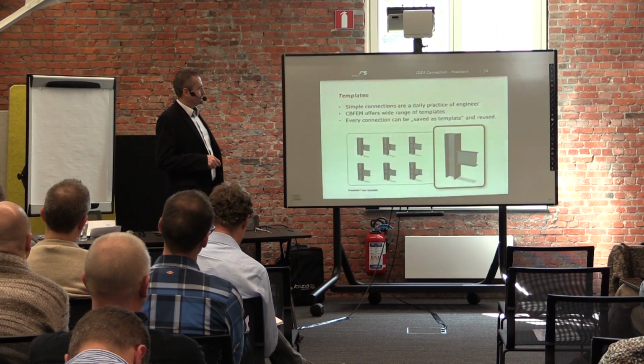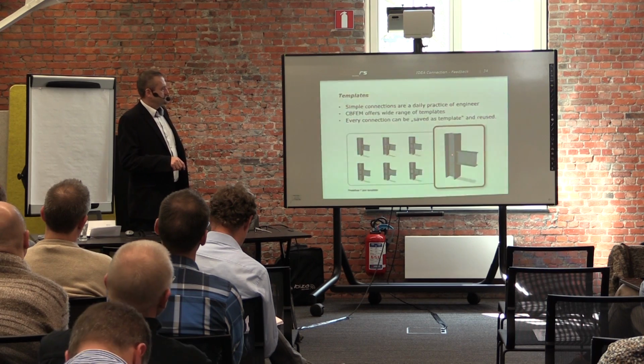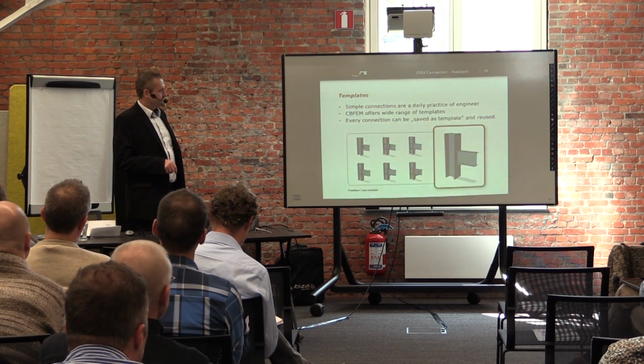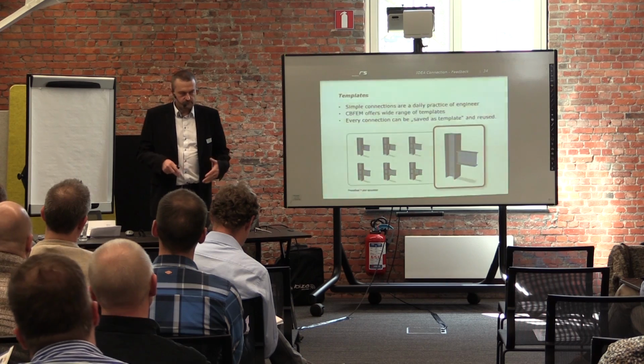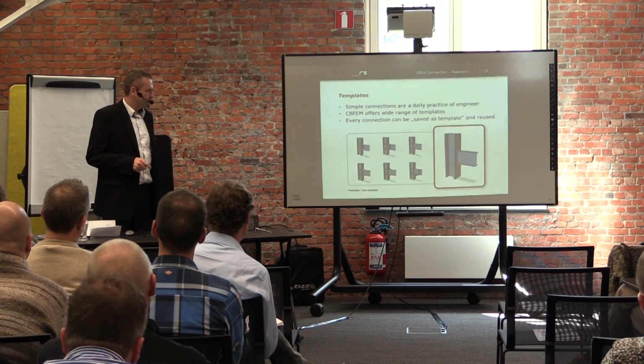We wanted to have our software very general for very sophisticated connections, but we want to keep it also very simple and fast for basic tasks and common connections. Therefore, we introduce templates. It means that when you create any connection in the software, you can say save as template, and you can use this configuration for any other new project.